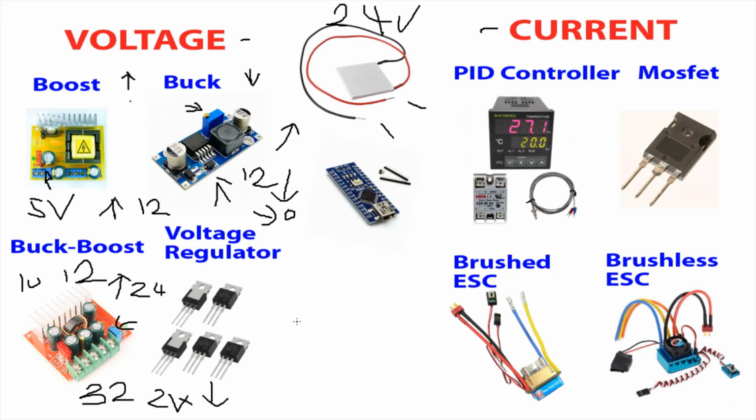So now we move on to good old-fashioned voltage regulators, which look like MOSFETs, and they are pretty much normally a static voltage, as in you buy a 5 volt one, so you apply whatever voltage to it and it outputs 5 volts regardless of input voltage, within reason.